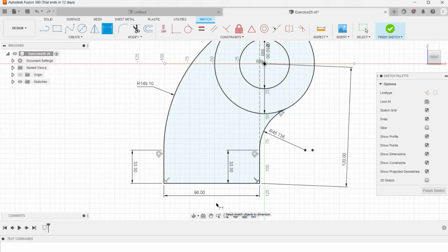Now downside also we need to make some other sketches, right? You can start sketching from lines. Initially we'll draw any arbitrary line and later on we can provide smart dimensions to this one. And again we need to draw one center line or construction line from here. From the middle of this one we can make a line. This will be a construction line.